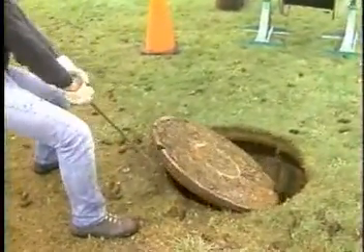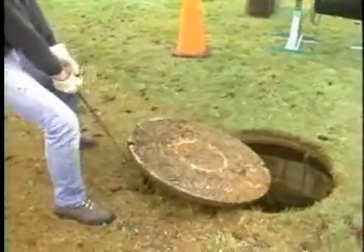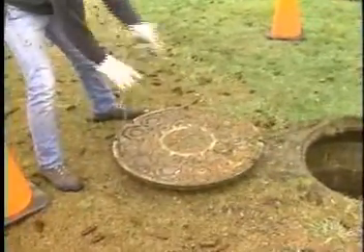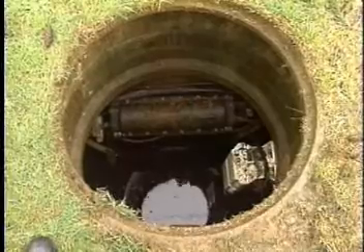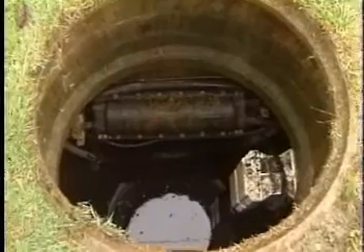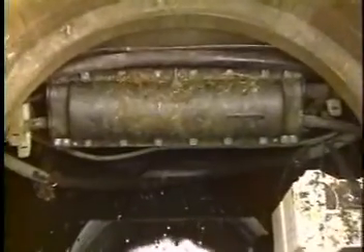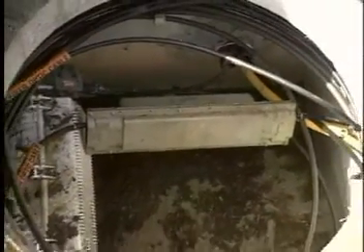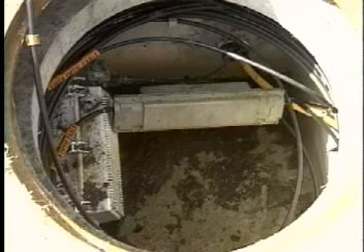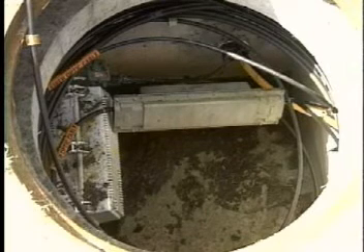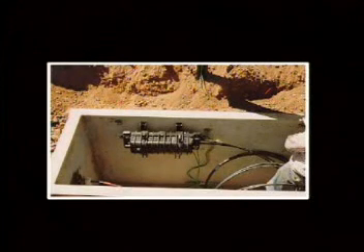Manholes are common forms of splice vaults and are most often precast from high-strength concrete with bonded reinforcing steel. The steel is then bonded to the wall inserts, which grounds the racking equipment. If the fiber optic cable includes metallic strength members or armor, these must be properly grounded to the manhole racking. If not, lethal electric charges could build up along the cable runs.